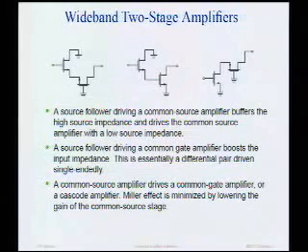But there's actually a better way to do it, and that's the amplifier that we all love, the cascode amplifier, right? The cascode amplifier takes a common source amplifier and buffers it with a common gate amplifier. And the reason this is so nice is, first of all, you notice here that I can share the same DC current between these two transistors. Here, I have to supply separate current to this stage and this stage. So even though this may solve my problem, it means I have to dissipate power. Here, though, they share the same DC current. So this is a really nice solution. It means that all of a sudden I fix my problem without having to dissipate more power.